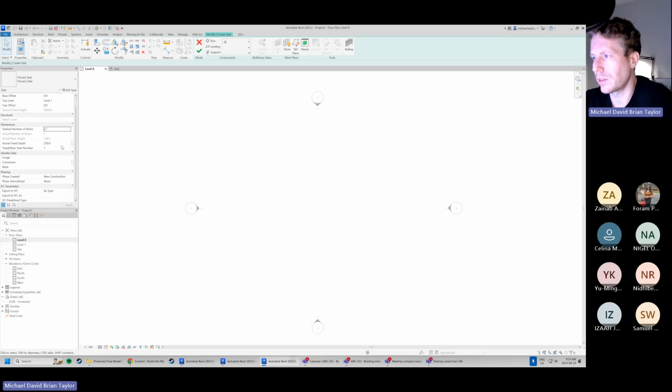A convenience stair is something somebody would take that's meant to be more comfortable, or more generous in terms of the space, right? So you might see something like a 300 millimeter tread depth here rather than this 250. Fire stairs, we're trying to keep as efficient as possible. And what I'll do is provide the risers and the tread depth. I'll see if I can post a little screenshot of the best in town variety. But for now, why don't we just jump into the tool?